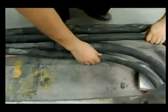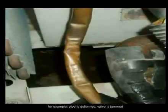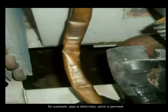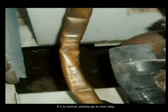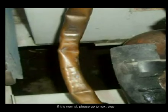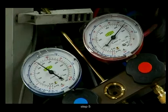Step 4. Check if the liquid side pipes are jammed. For example, the pipe is deformed, the valve is jammed, or the shutoff valve is not open, and so on. Check it one by one. If it is normal, please go to the next step. Step 5.